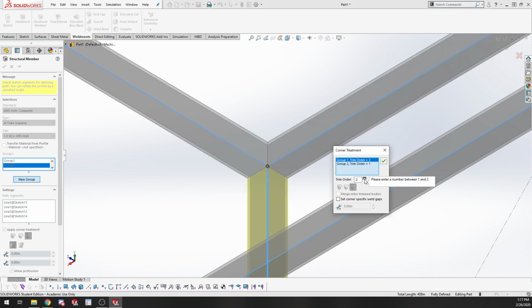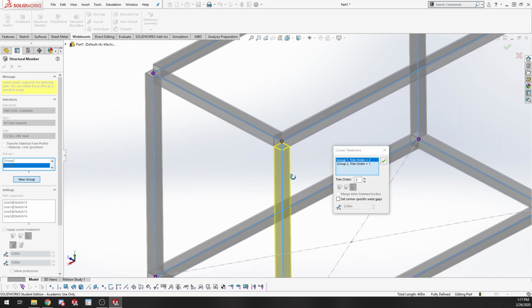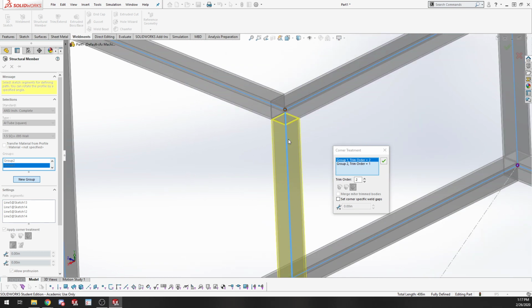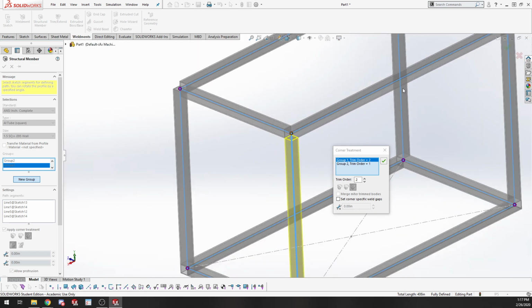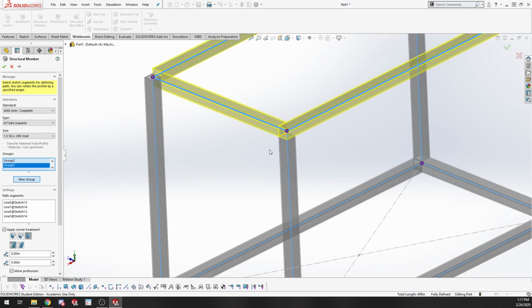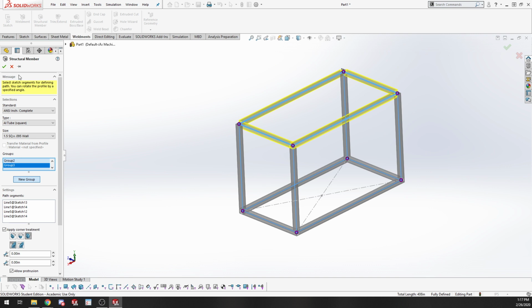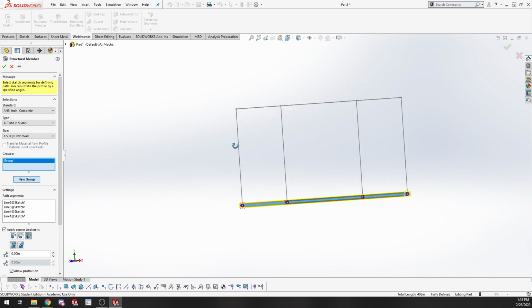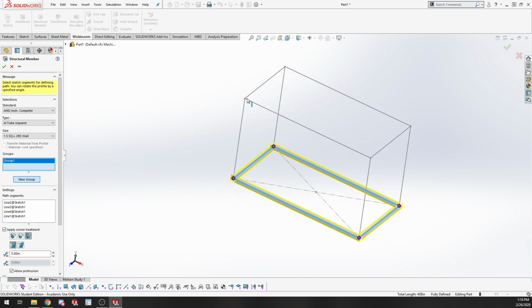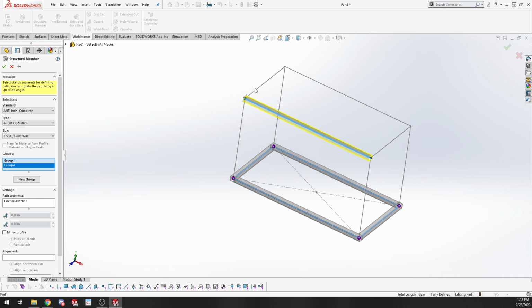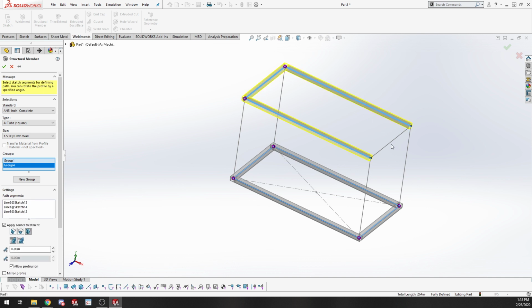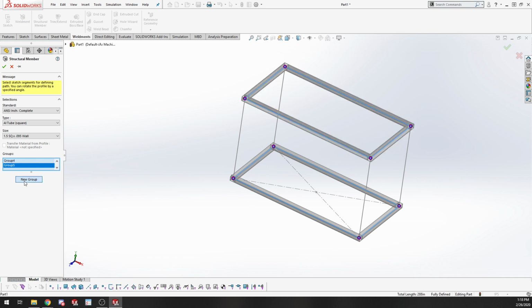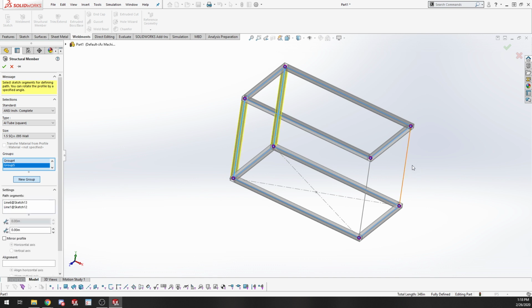And now if I make this one trim order 2, you can see that this tube is now getting trimmed against my trim order 1 group. I can do all those individually, but the best thing to usually do is, as you're going through adding them all in, when I make my new group, I'm going to do the next one there. It's standing alone, and then I'm going to make the group that gets trimmed against both of those.